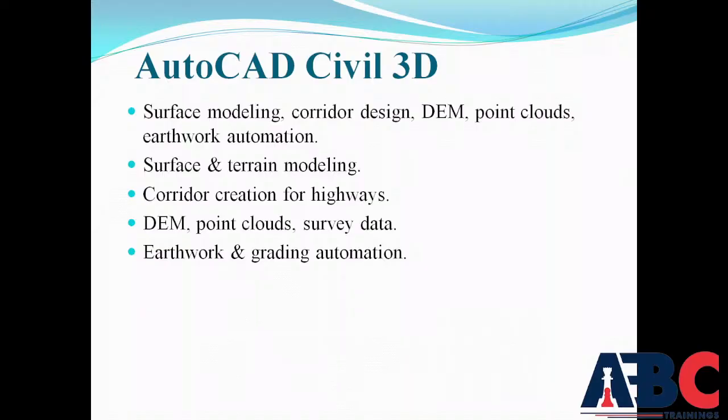Corridor in Civil 3D is used for designing roads, highways, rail alignments, and pipelines. It means integration of alignment, profile, and assembly. When we are making a highway, railway, or pipeline, we make one integrated alignment for it. Alignment basically means a route, with 3D roadway geometry and dynamic updates. If the roads are not good in direction or plane, or if there is a wrong slope, then accidents and other problems happen. So it is a very important thing, and we do it using AutoCAD Civil 3D.